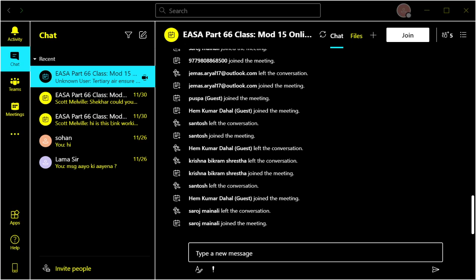And a lot of new cars nowadays will have a magnet on there. Not for diagnostics, well, it does help, but any little bits of debris, it stops those little bits of metallic debris swimming around the bearings on your engine. And a lot of cars are doing that now as well, which is quite a good idea. Okay, that's a basic one.